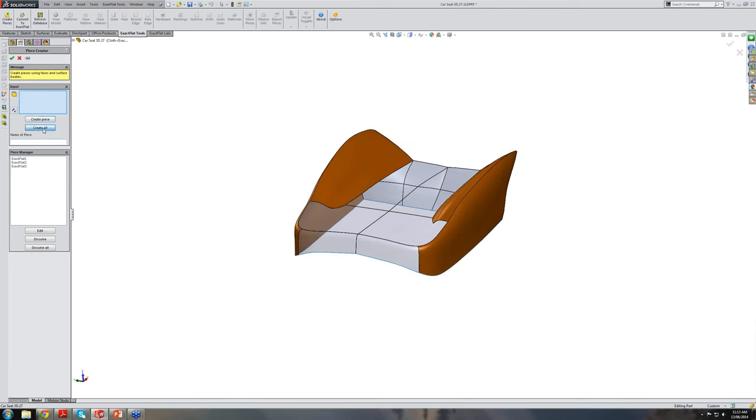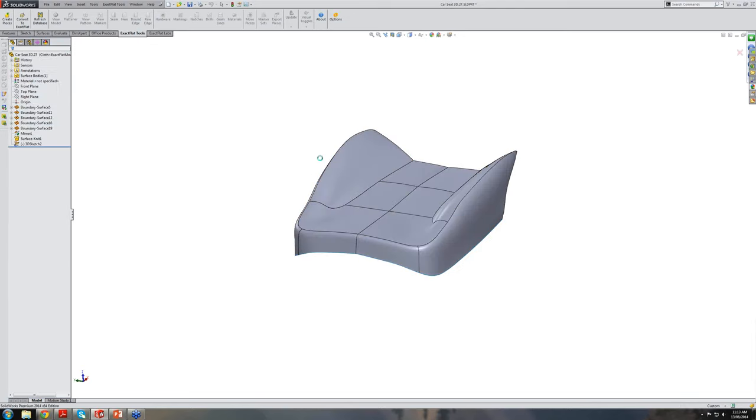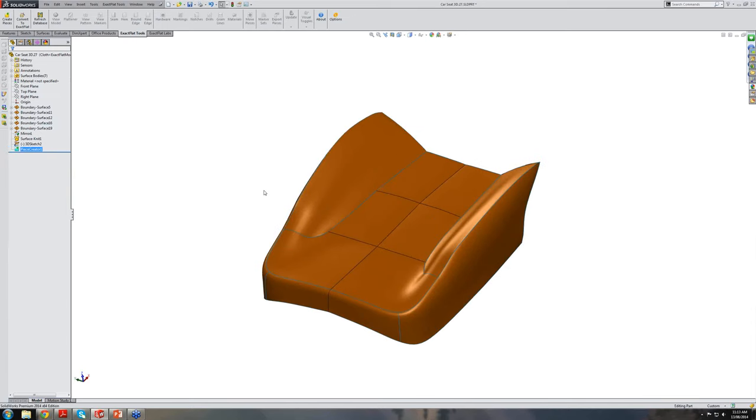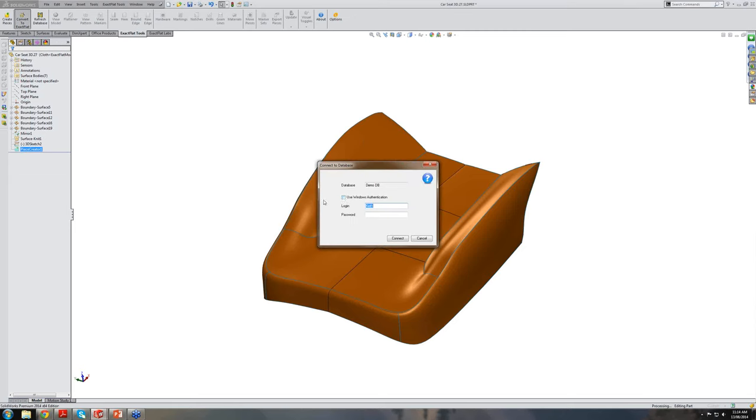Once a piece is created, it will become transparent, and it's locked for editing, as you can see there. With the transparent pieces, the model will allow you to select through layers as well. So if you have a layered product, for example a removable insulation blanket for a valve and piping system, you'll be able to select through those layers and manage multiple layers, like in a carbon fiber layup or other things. Okay, so once we've done that, we just click Convert to ExactFlat.